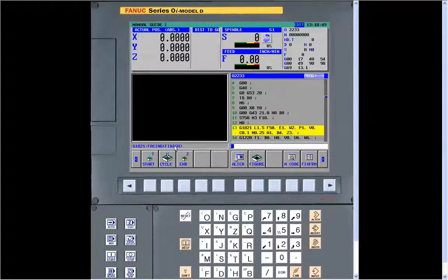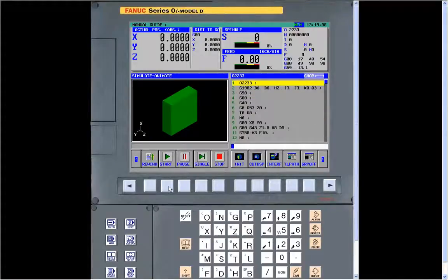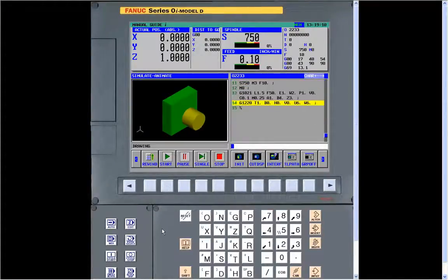The one before is our facing finish. Those are the only 2 lines of code that we need to do this facing cut. And as we did before, I like to simulate it as we go through each cycle. So at this point, we go to Auto, Simulate, Rewind, and Start. So there it milled the face of that part, just cleaned it up. The reason we have this alarm is because we don't have an ended program. But it did what we wanted it to do.